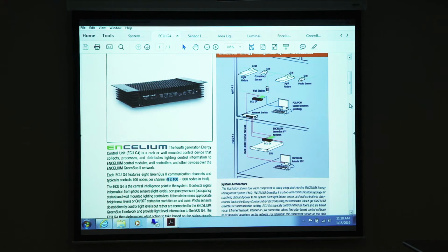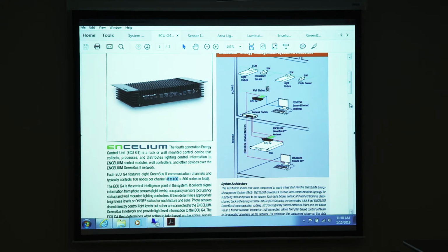Right? So you're using the SSU to help program a new ECU. Yeah. Using the backup information from the SSU to program the new one. Yep, exactly. So the question is, you're using the SSU's capability of creating a snapshot or a backup, right, to recreate ECUs if you need it, right? And that's correct. And that's the reason why after we finish a site, we take a snapshot or a backup. We bring that into the office and we put it on our server. So over time you guys can make changes and whatnot, but we have the final backup that we left with the site. So if anything happens, we can restore it, right?